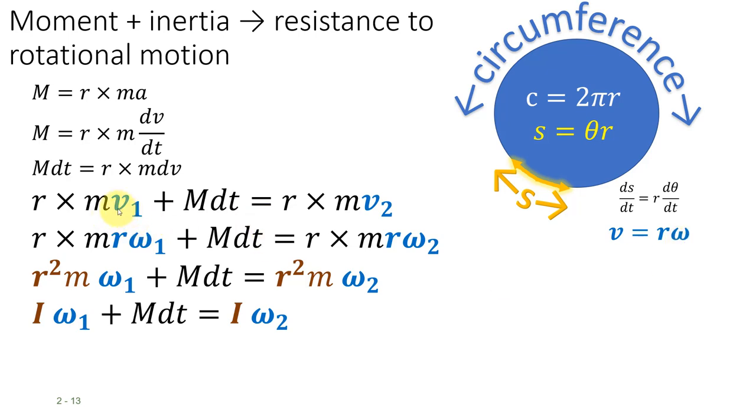Okay, so let's go ahead and substitute out our velocity for the radius times radians per second, our angular velocity. So r omega is equal to v, and this r omega is actually tangent to our circle. So if you look at the velocity, it's tangent. That's very handy for the cross product because this is 90 degrees to our position vector.